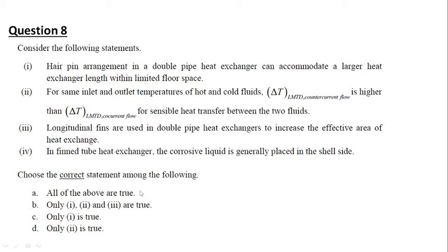The hairpin arrangement in a double pipe exchanger accommodates larger heat transfer length within the limited floor area. Also, the LMTD of counter current flow is greater than co-current flow for the same inlet and outlet temperature, and the fluids for sensible heat transfer between the two fluids. But here it is a sensible heat transfer only, that is, there is no phase change.